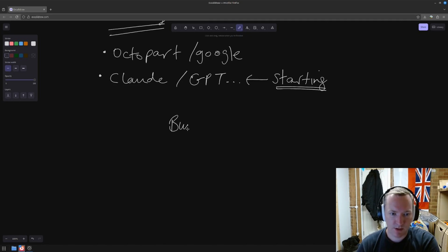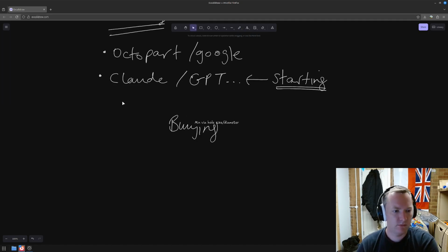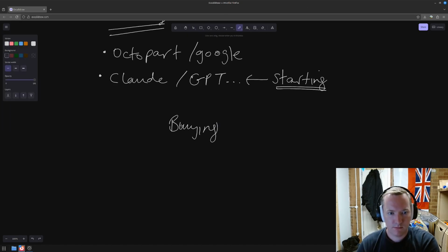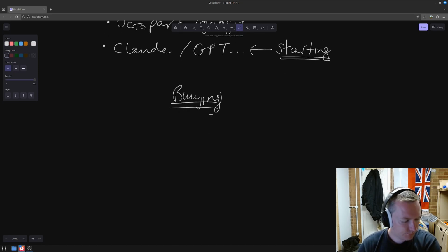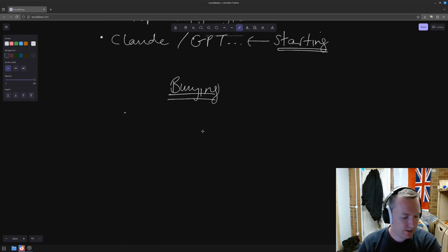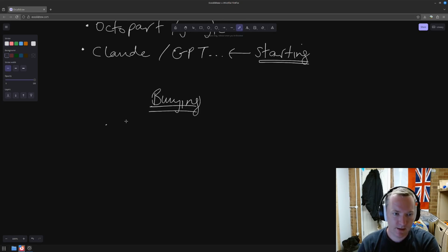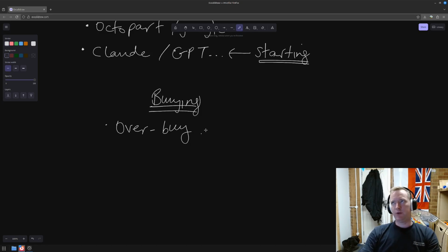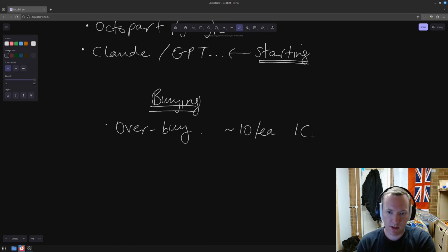So we've identified the parts that we want. So now we have to buy the parts. It seems straightforward, right? You just find the parts you want and you buy them. Well, something I would suggest is over buy. So if you do a PCB run and you only get 5 PCBs, I typically like to get around 10 of each IC, and I like to get 100 of passives.